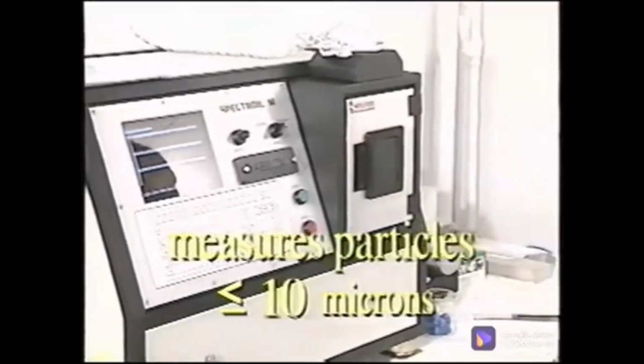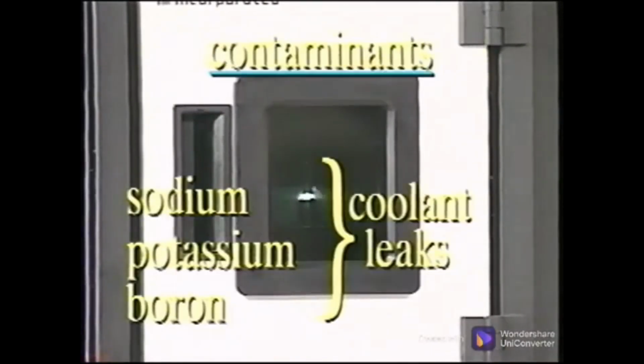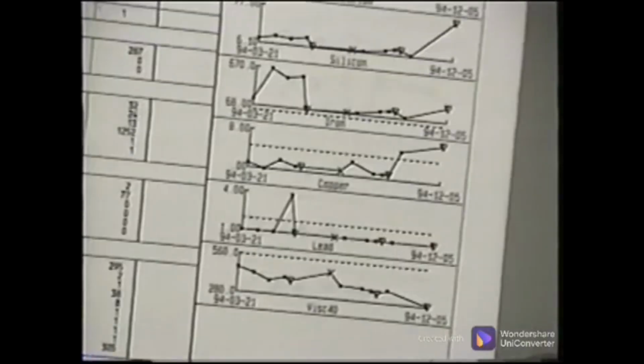The elements are recorded in parts per million for particle sizes less than 10 microns. The tests detect and measure contaminant metals, additive metals, and wear metals. Contaminants such as sodium, potassium, and boron are indicative of coolant leaks, while silicon is from dirt getting into the system. Additive metals in the fluid can indicate the level of degradation by measuring the depletion of the elements that